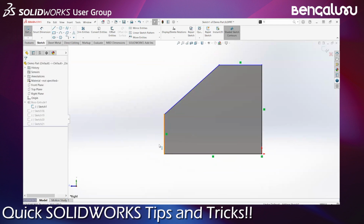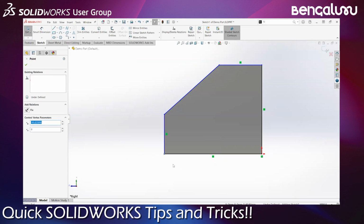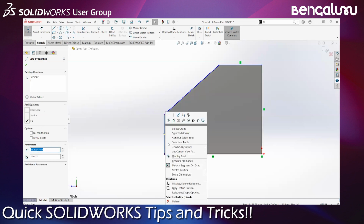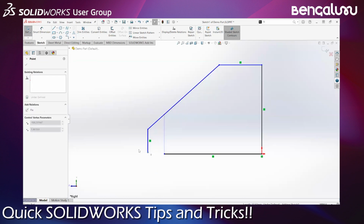But today if I extend this sketch, you can see that even this line segment is getting affected because of the constraints they have. So instead of deleting these constraints and then moving this line, a quick way to do it is to click on a line segment and right click. You'll have this command called detach segment on drag. Once you click on it, you can see clearly that it is checked. It's active now.